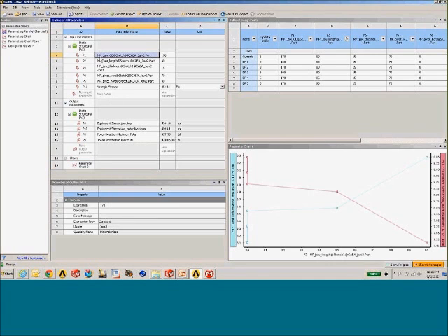Now we can make associations between these parameters by picking on one parameter and substituting its expression with an alphanumeric expression that relates to another parameter. So if I had a mesh control in this case and I wanted to make it a function of this jaw OD, I could pick that mesh control and substitute the numeric value with some alphanumeric expression, like for instance P1 divided by 10. So I'd always have 10 divisions along that dimension on the CAD side or on the mesh side.